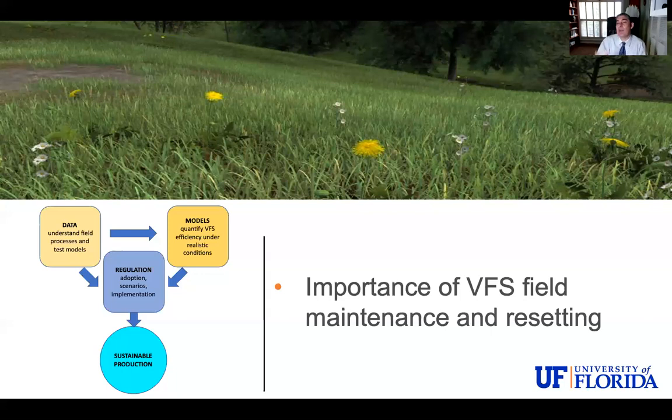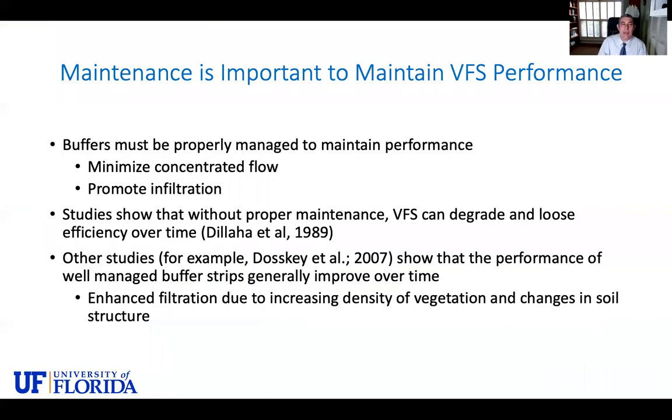And this is a cycle of about 5 years. Then you're going to have to mow to maintain it at the perfect, our nominal conditions. Because if you don't do it, there are these studies that indicate that unmaintained buffers degrade in time and lose efficiency. Not surprising. So basically what's going to happen is that if you just put the vegetation and you don't maintain it, it's going to be like everything else, it's going to break, and then you don't have the credit or the expected efficiency that you would assign to the buffer as if you were to maintain it.